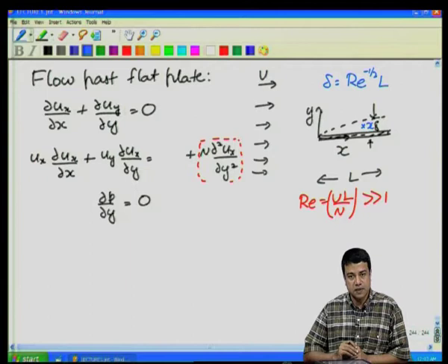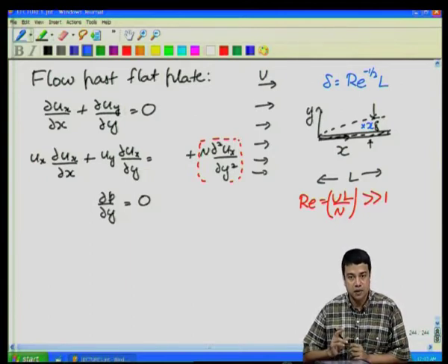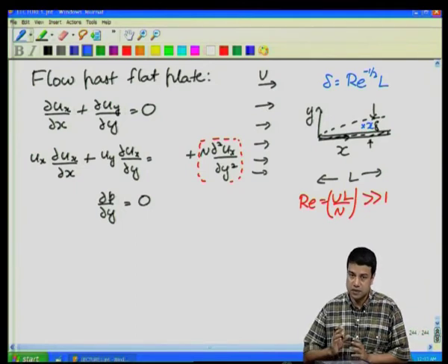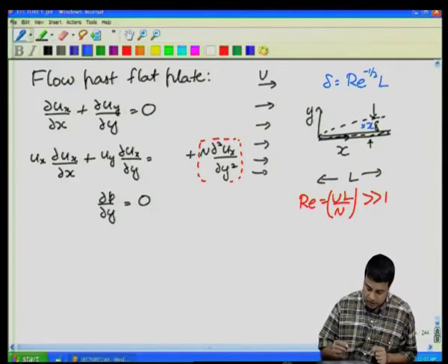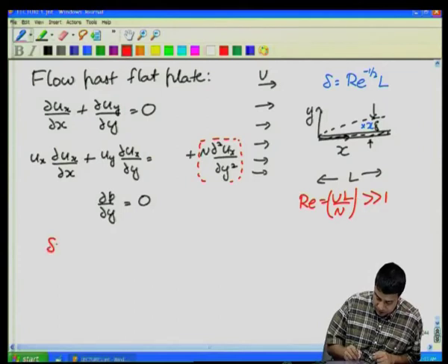So, on this basis one can define a local boundary layer thickness for the situation where the flow at a given location x does not depend upon the total length L. To obtain that, you just substitute x for L in my boundary layer thickness definition, because I should get the same flow dynamics even if that plate were only of length x, because what happens downstream does not matter. So, on that basis we have defined the boundary layer thickness delta is equal to (nu x by U) to the power half.